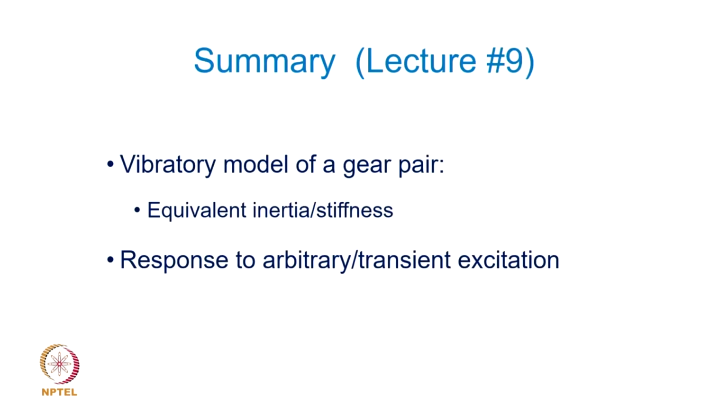What we discussed in this lecture is how a gear pair in a vibratory system is modeled or can be included in the model of a vibratory system. In that context, although the gear pair can also be accounted for by looking at the forces on each of the gears, in this case we focused on the energy based method.